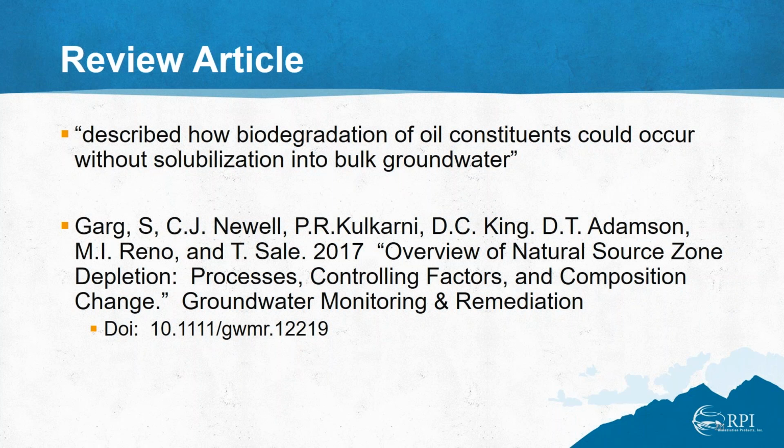In fact, what we do is we design the sulfate, the TDS, if you will, to be right up there towards the upper limit of what the bugs can tolerate. So then what happens is, initially, there's no demand on the gypsum. There's now a demand on the sulfate that's dissolved in the slurry, the water that the slurry was created in. So that sulfate goes away, and then as that's depleted, now the gypsum starts to kick in. So that's one way in which we've attempted to put additional terminal electron acceptor in.